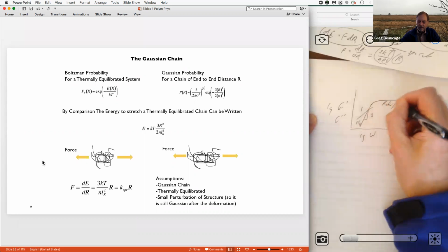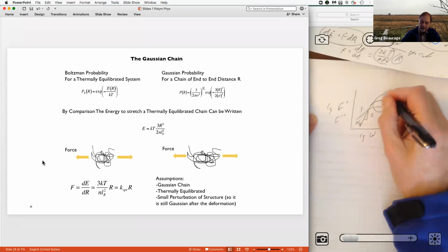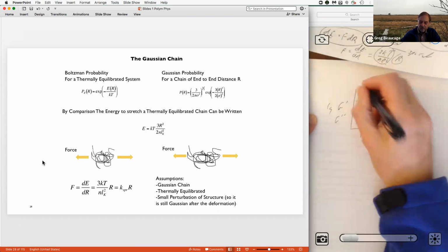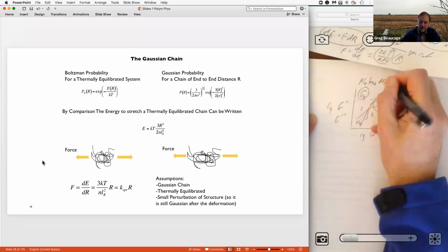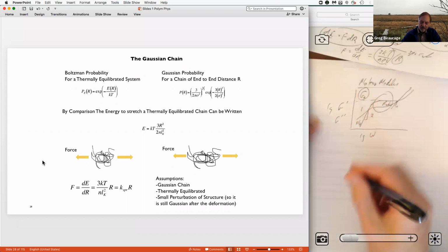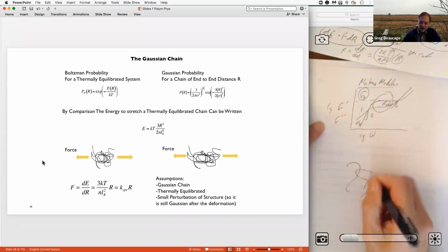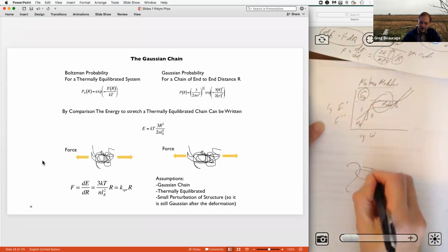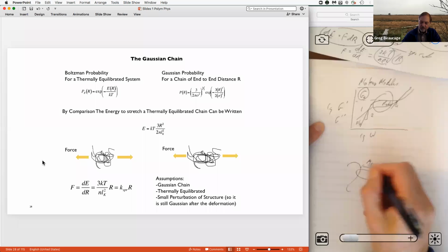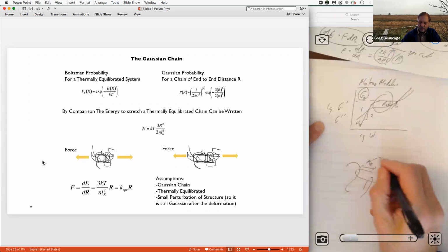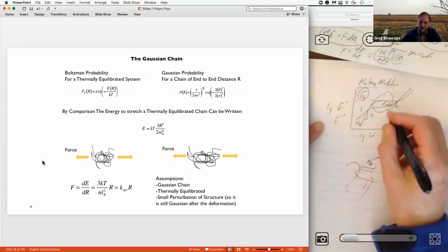And then it does some other stuff over here, it crosses over again. Basically, within this rubbery plateau, that number is called G naught, the plateau modulus. Right, and at that point, the scenario is that the chains are like hooked together, right? And there's some molecular weight ME between the chains, and we talk about that from that plateau modulus, you can get what ME is.